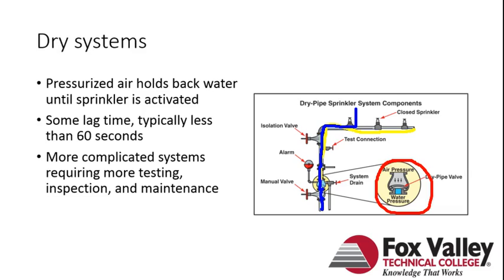It is a little more complicated than a wet system. There is some lag time. It should be less than 60 seconds. It all comes down to the size of the system and how long it takes all the compressed air to flow out. It does take a little more time in testing, inspection, and maintenance than a wet system does, though.